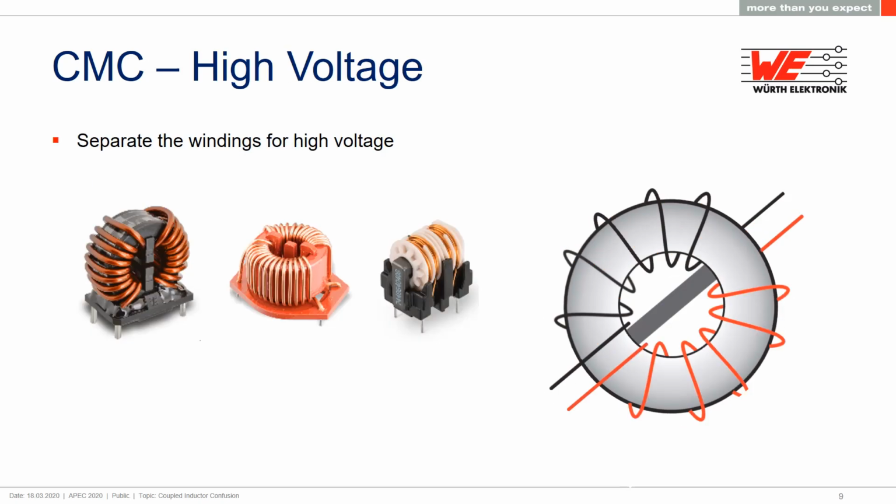In high voltage applications, you just separate the windings from each other. They're still going in the same direction around the core as you've seen earlier. You can see why polarity dots, which aid in proper connection, are important. Here you have a gap between the windings to meet safety and spacing requirements between the high voltage lines. There's usually some kind of plastic spacer to mechanically secure the spacing, which has to be guaranteed.